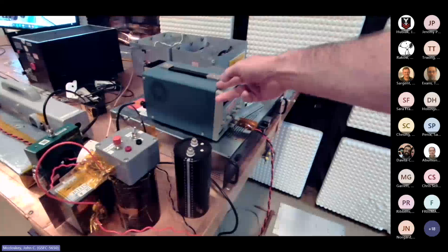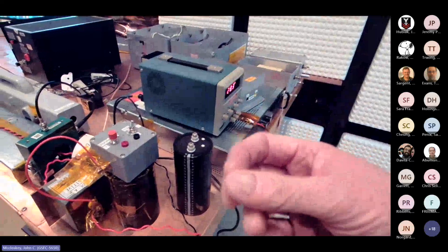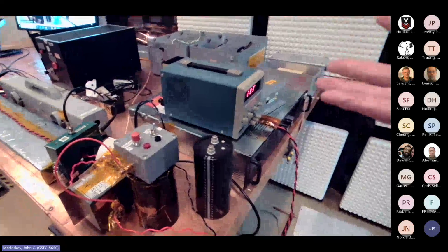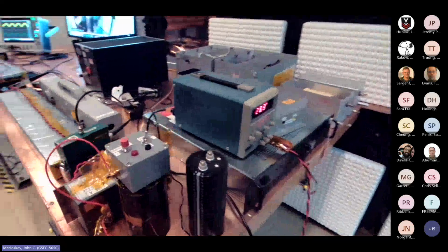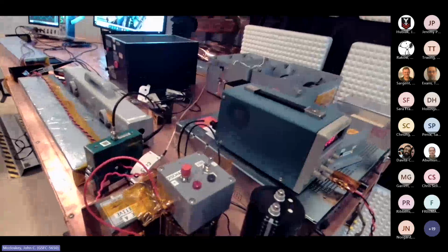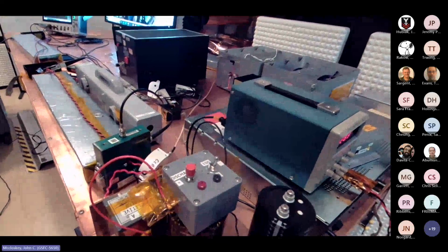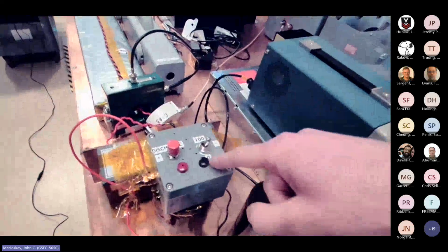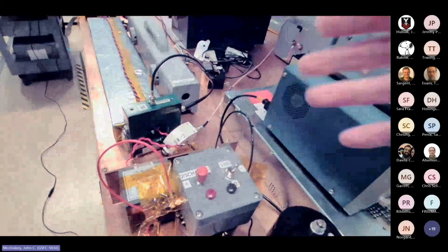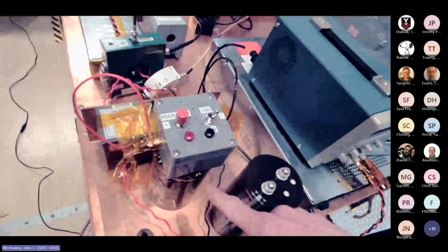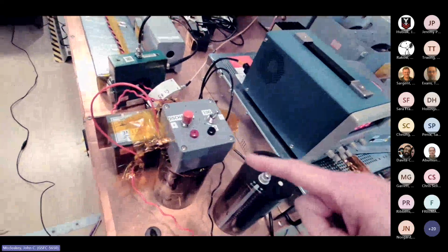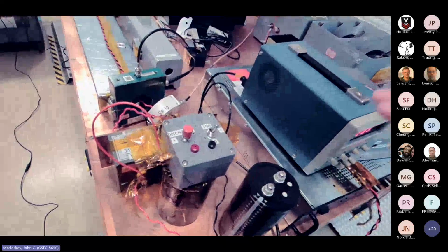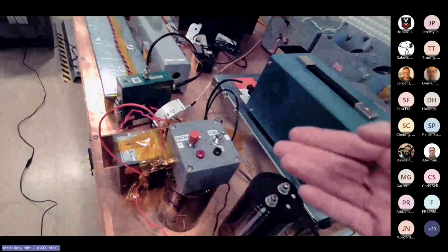This supply does fine with it. But some supplies, I think some of the more modern, like microprocessor controlled supplies, if they go into current limiting, if you don't override the setting, I think some of them will shut down. And so for that kind of situation, putting a 100 ohm resistor, we just picked 100 ohms. There's nothing real magical about that value, but 100 ohms give or take, in series with the capacitor, gives you a smoother charge up rate to put less strain on the power supply while it's trying to charge it up.